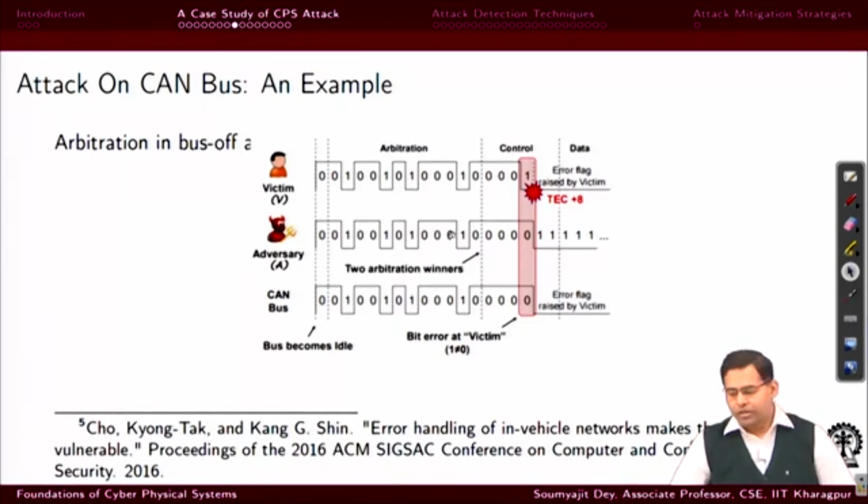Let us understand this, because this is not how the original CAN system is designed, right. In the original CAN system, a designer who wants his system to work will never have the same ID for different messages coming from different ECUs. But this is the adversarial scenario, right. The adversary, sitting in some ECU, or in a newly attached malicious ECU coming from a rogue service center, or due to some code download which should not have happened, is trying to send messages with exactly the same ID as the victim, right.